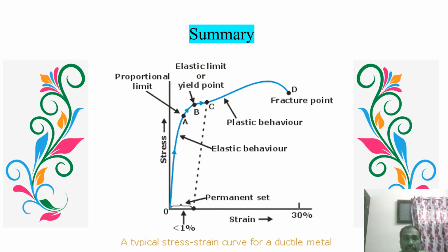And finally, as a summary of today's lecture, I talked about elastic moduli. If you apply stress to any body, strain is going to happen. The stress is proportional to strain within the elastic limit. This is shown graphically. If you apply stress on that body, the strain increases up to the particular point B. This is called elastic. B is called the yield point or elastic limit.